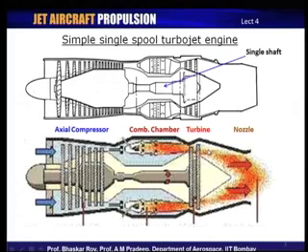It releases that gas through this nozzle, and the nozzle is appropriately shaped. For every particular engine, it needs a particular shape, and it is released through that nozzle into the atmosphere through an exhaust system, whereby the exhaust velocity is very high, certainly much higher than the intake velocity with which it came in. And of course, this change of velocity manifests itself in the form of production of thrust.